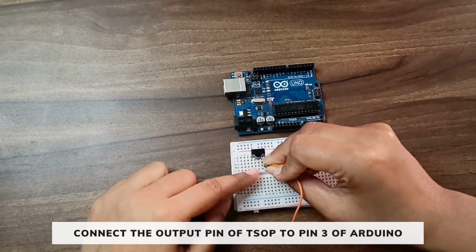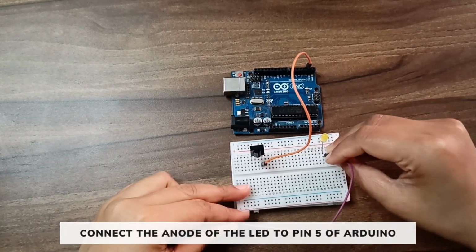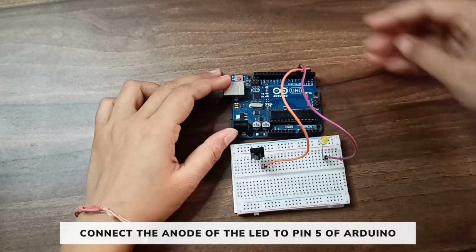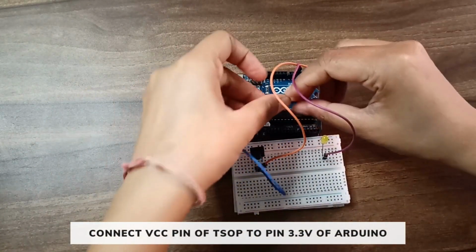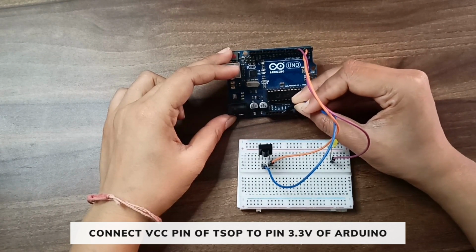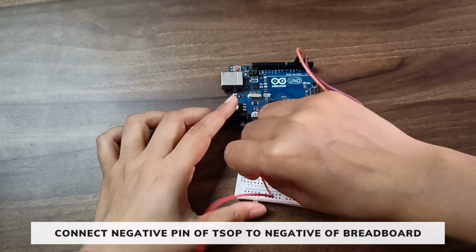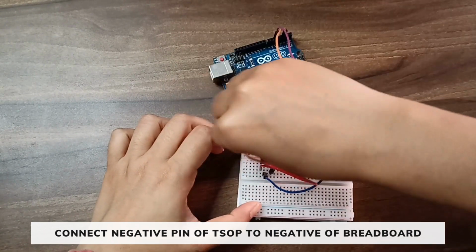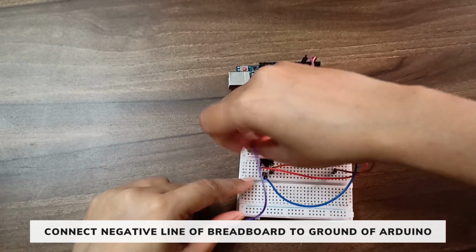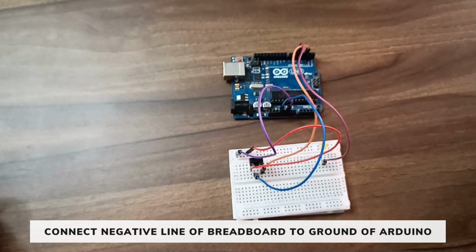Now take some jumper wires. Connect the output pin of the TSOP to pin 3 of the Arduino, the LED pin to pin 5 of the Arduino, the VCC pin to the 3.3 volt pin of the Arduino, and the ground pin to the negative line. We are making a common ground. Take another wire and connect the negative line to the ground of the Arduino. So our assembly is done.